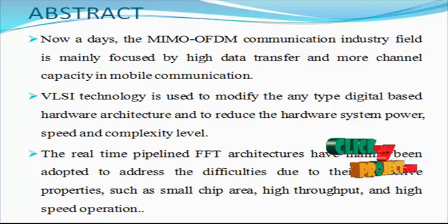Multipath architectures are often adopted when the throughput requirement is beyond the theoretical limitation that the single path architecture can offer at the given clock frequency. However, they require concurrent read or write operation for the multipath input and output data. Therefore, the single path architecture could be appropriate in some cases when the system cannot ensure the concurrent operations. However, the arithmetic utilization is low compared with the 100% utilization of existing FFT architecture methodologies.